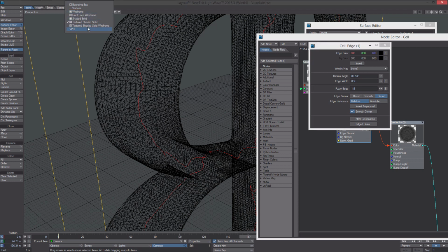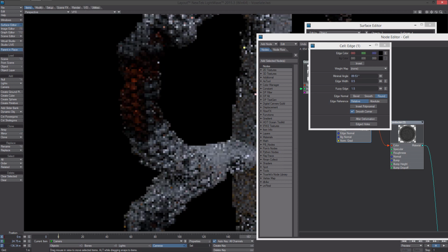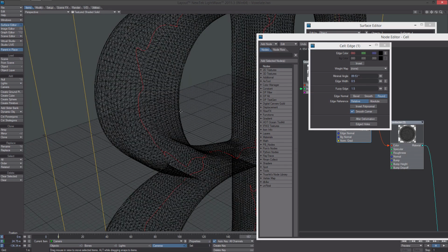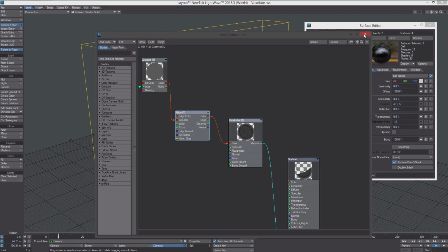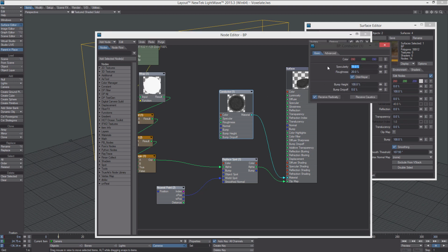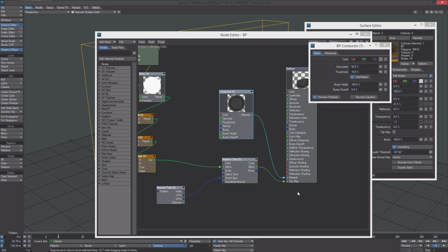I'm just messing with the settings here. I probably could have left all this out, but I wanted to just show you a little bit with the surfacing, just so you have an idea of the kind of thing you could do. So right now I'm just going to turn the specularity to 50, turn the roughness to 10, and I'm going to turn that color up a little bit so I don't have to turn the GI up so high, to 120.